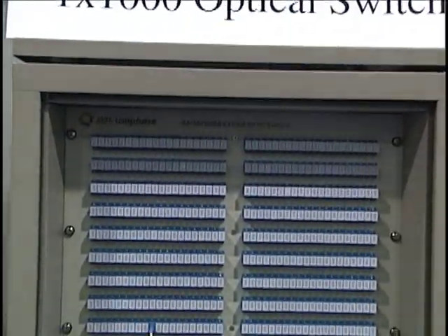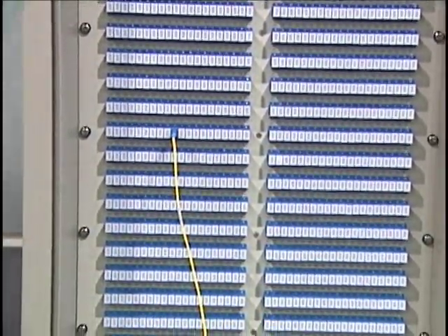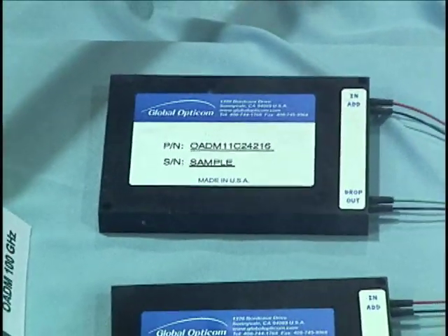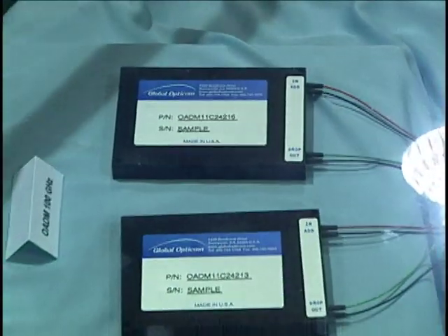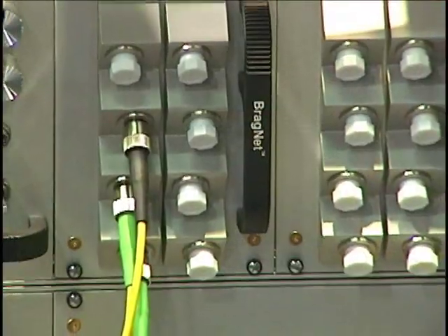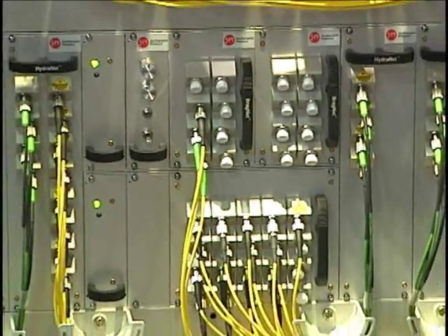Optical switches grew with the technology, with switches handling fiber counts up to 1,000 ports using a variety of techniques. Key elements of the optical add-drop multiplexer, or OADM, are the optical circulator and the fiber Bragg grating. These components allow switching of wavelengths by adding and dropping them through the optical ports with no fiber movement.